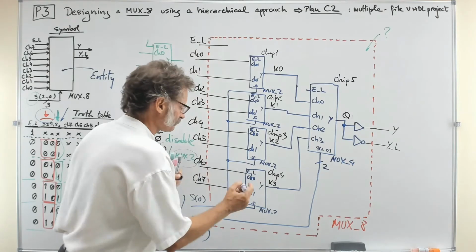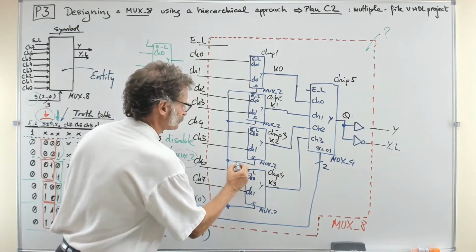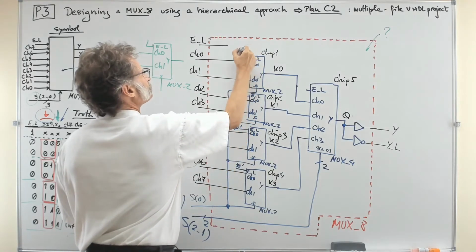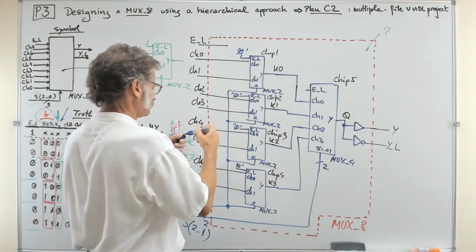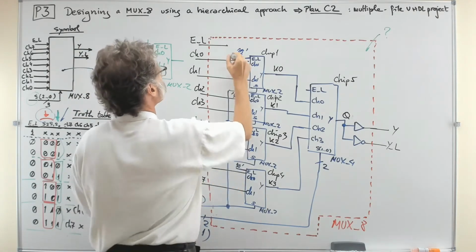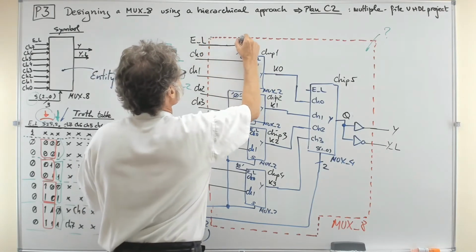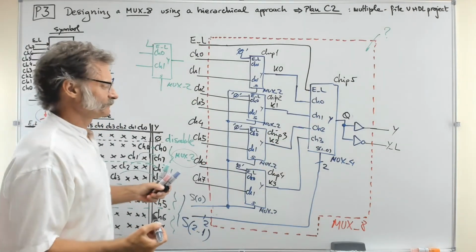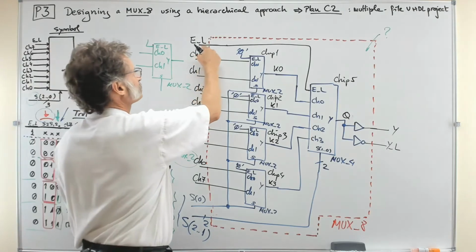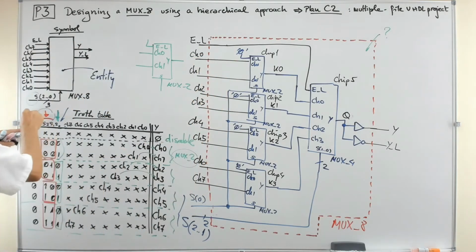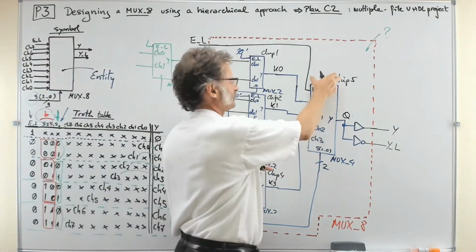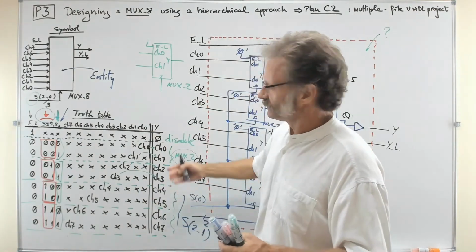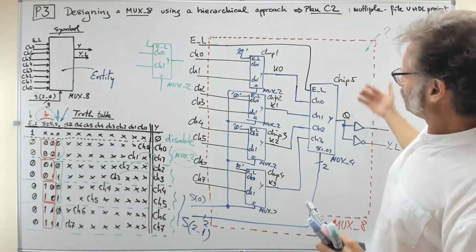You can do it as you like, but for example, you can connect all the time these to 0, these to 0, the enable connected all the time to 0 in this initial stage, and then you can connect, if you like, the input port enable active low straight to the enable active low of the chip 5, because in this way, if the general enable active low, the one in the truth table, is 1, this device is going to be blocked because it has a similar table like this. Absolutely. So this is perhaps the final circuit.